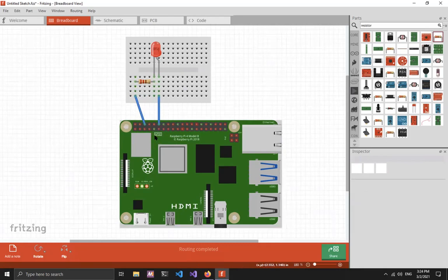If we output a high voltage, which is about 3.3 volts, it's within the range that's recognized as a logical one. So that will output some voltage here, and the current flows through this LED, through the resistor, and to the ground that completes the circuit. Okay, so this is our Hello World circuit on a breadboard.